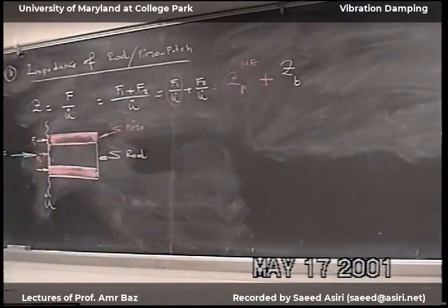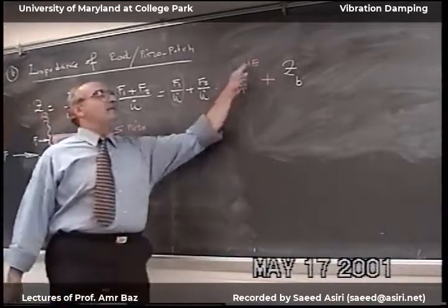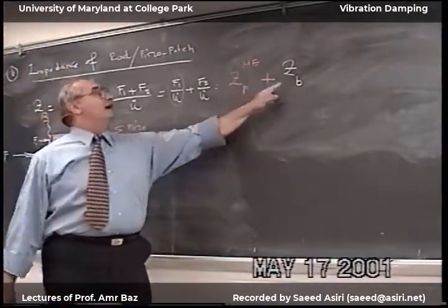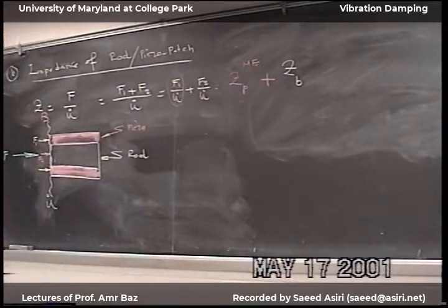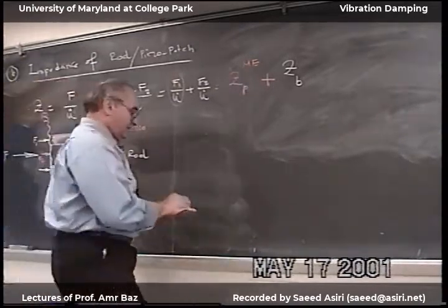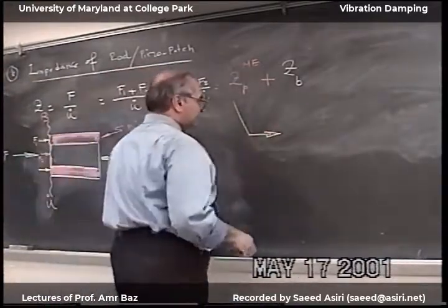So now accordingly here, the impedance of the composite, which is in our case here, section B, will be made of two components. Z mechanical piezo, which we know how to get. Z base rod, we know how to get, because Z base rod is the same like this Z, which is EA, wave number K divided by omega. Okay, so we know how to get the Z. Now, Z mechanical for the piezo,